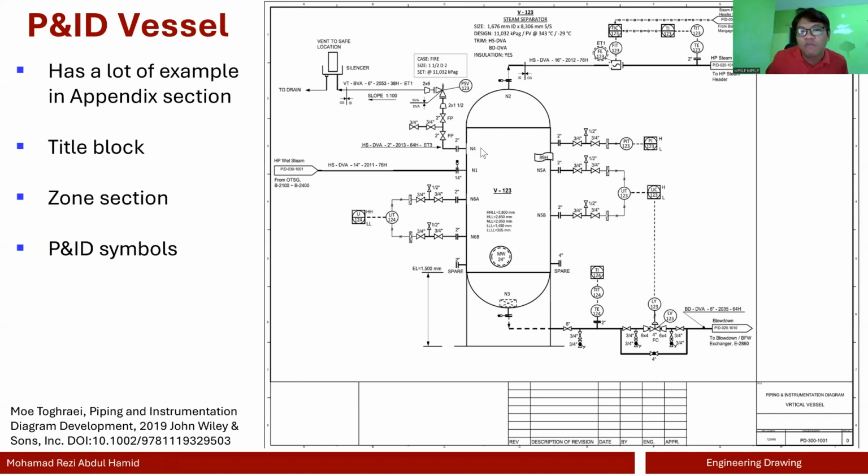This is nozzle number 4. And then maybe you write down, please refer to section C3. So instead of looking throughout the entire drawing, they just go specifically to C3, and they will see that a new symbol has been added. The zone section allows the reader to go directly to a specific section or location in your drawing.